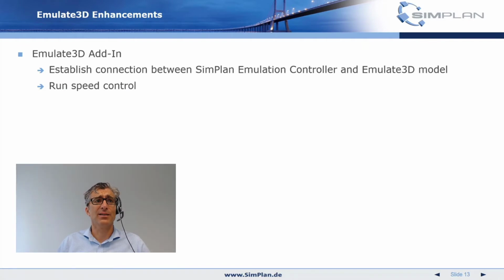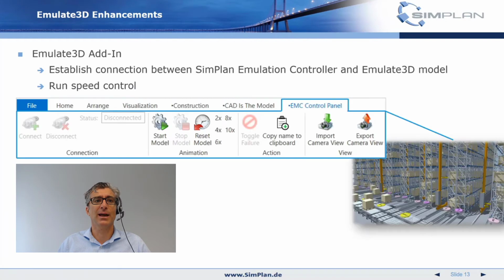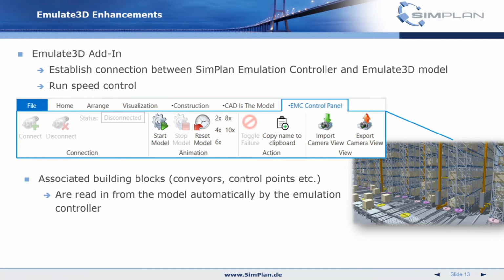We also have enhancements in Emulate 3D itself. We developed an add-in where you connect to the emulation controller, reset, start the model, and set the run speed. Our experience with high-level emulation is that you can accelerate the simulation speed up to 20 times real time. So we can test much faster than real time, which is much appreciated because you want to test an overall system.